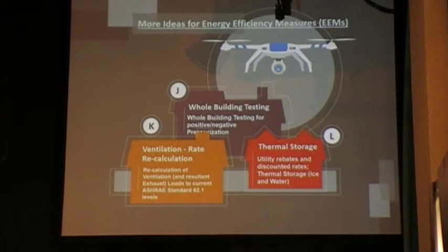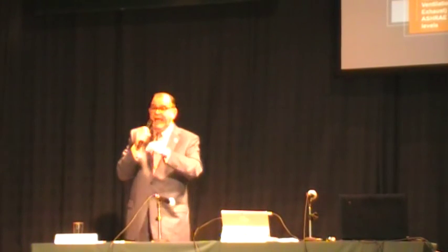So we make the building tighter, we don't send that energy outside, we keep it. Ventilation, the current ASHRAE standards allow for us to reduce the ventilation loads in a building, so if the building is like 10 or 15 years old, we can reevaluate that ventilation and exhaust per the current standards and actually save some money and still be doing the right thing, right?